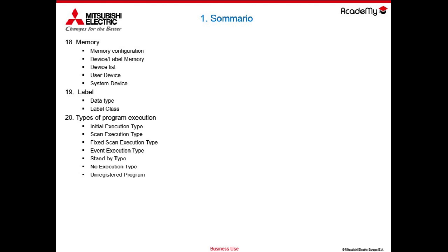We mentioned the program containers. We can call them program organization units. These will be put into operation by the PLC and therefore scheduled on the basis of the type chosen by the user among those available by the PLC scheduler. We will depend as much as possible, in a basic course, on the different types of execution listed here.